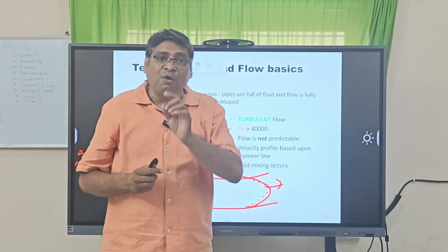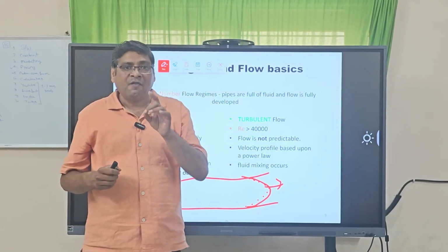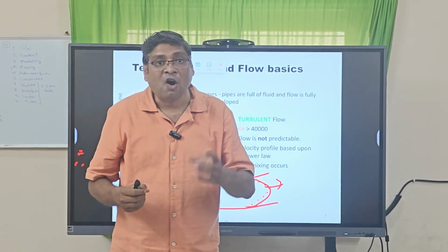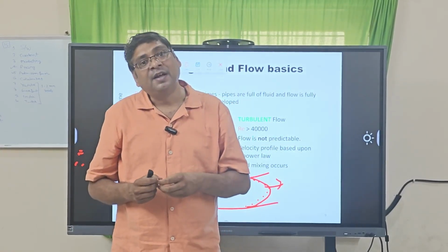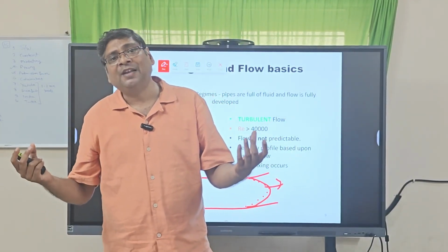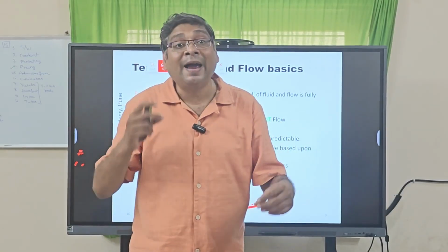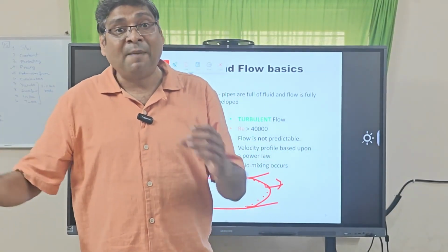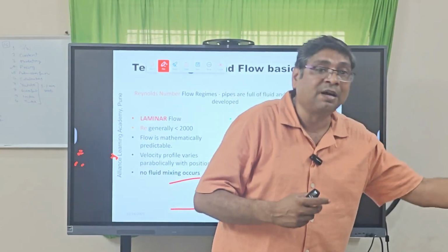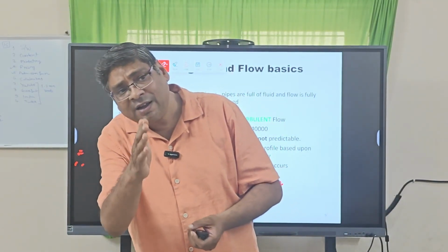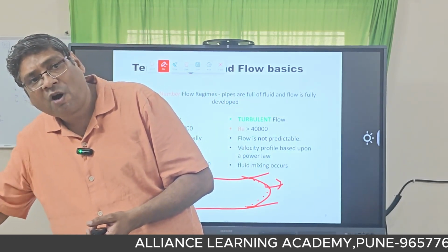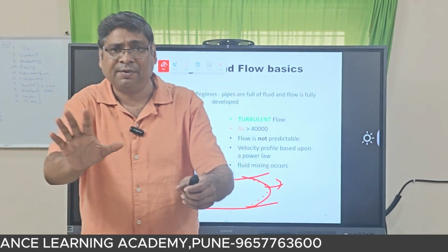That's why for any flow meter, while installing, we have to follow the manufacturer's guidelines on how much straight run I need before the flow meter and after the flow meter. Technically we say upstream and downstream. Upstream means from where water or fluid or gas or steam is coming, and downstream is where it goes out from the flow meter. It may be steam, gas, water, acid, whatever fluid it may be.